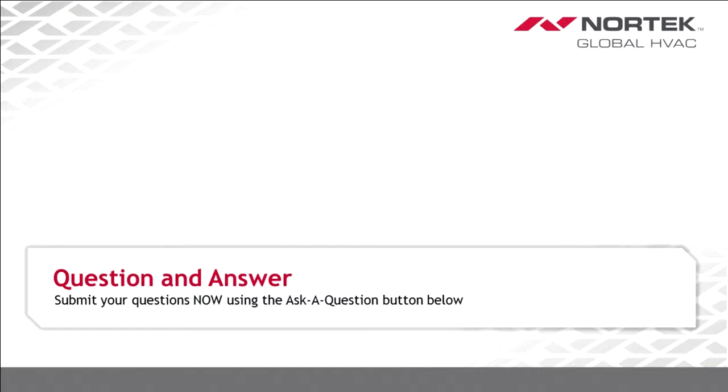Okay, I'm sorry, Dana, I missed the question. Could you repeat it for me, please? Sure. So the question is, what if neither test is conclusive? And then they go on to say, I had a furnace that absolutely would not make the pressure switches. Smoke test was fine. So it sounds like they couldn't get the pressure switches to make, so they did a smoke test, but it looks like it passed the smoke test. Okay. All right, I got you now.